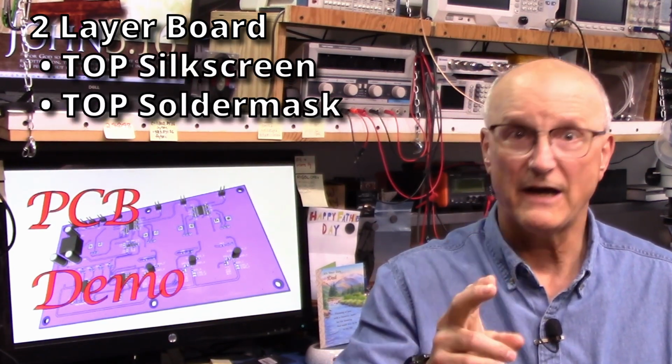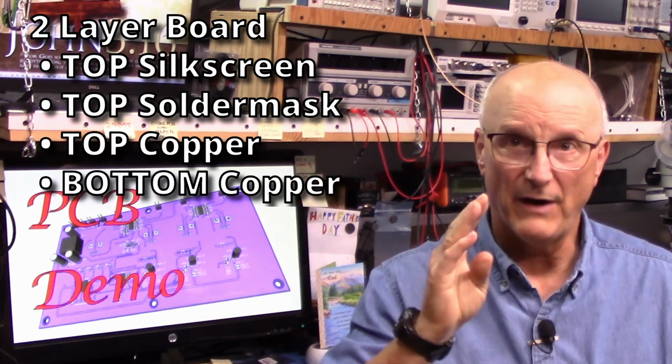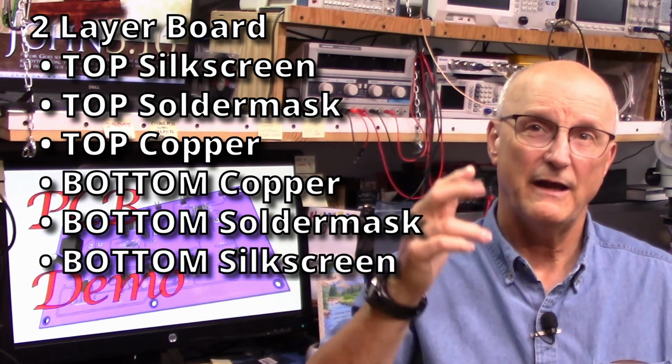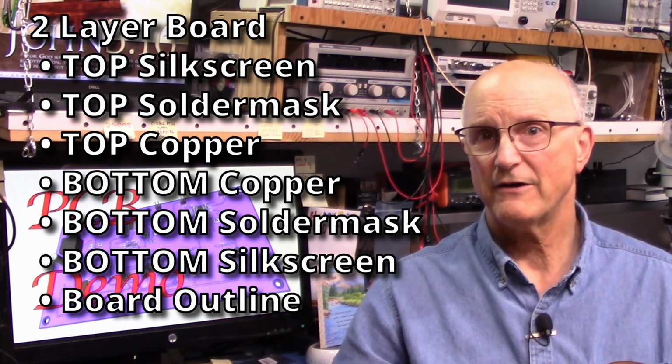So, on a two-layer board, you can expect the following Gerber files to exist. There's the top silk screen, the top solder mask, the top copper, the bottom copper, the bottom solder mask, the bottom silk screen, and then the board outline. For each additional layer, you add another file.